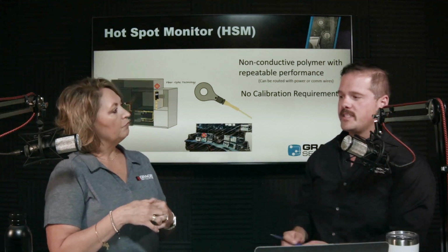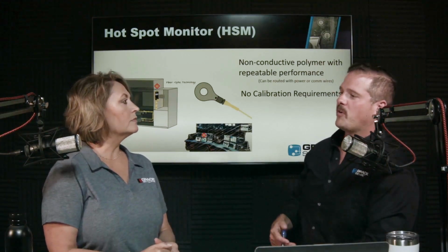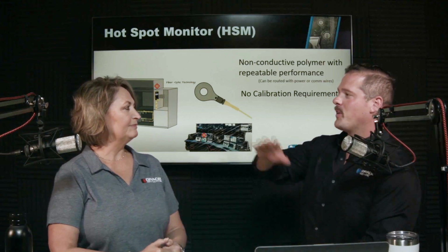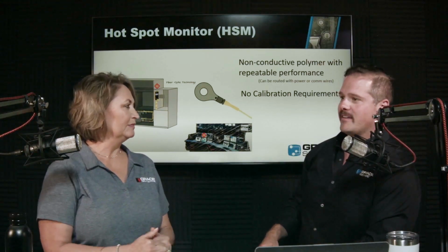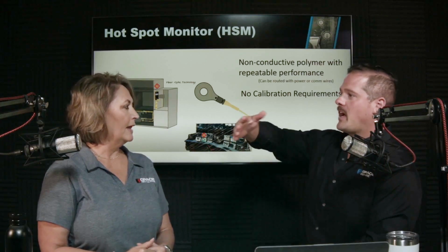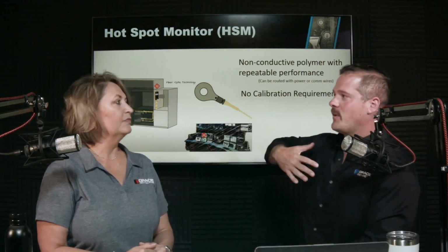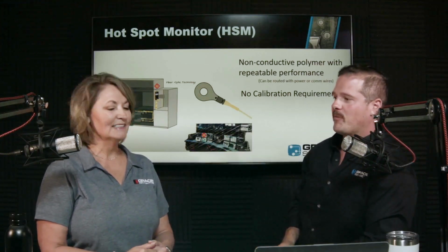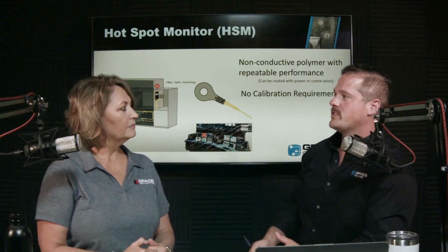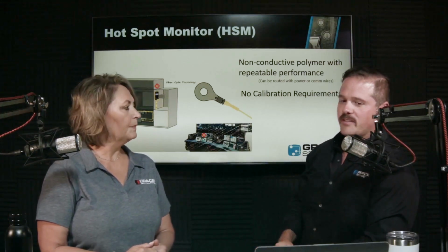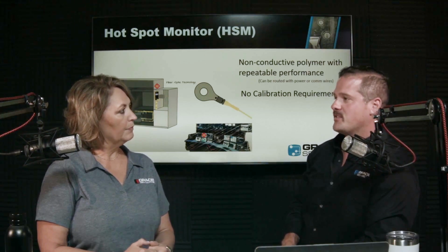Yeah, I've seen some videos of bus bar on motor inrush currents, and all this. It looks like you're in an ocean of copper moving through as that sine wave pulses through the copper bus bar, and so the stress on these joints on any sort of on or off motion is pretty substantial. It's a really fascinating thing to see those kind of physics.